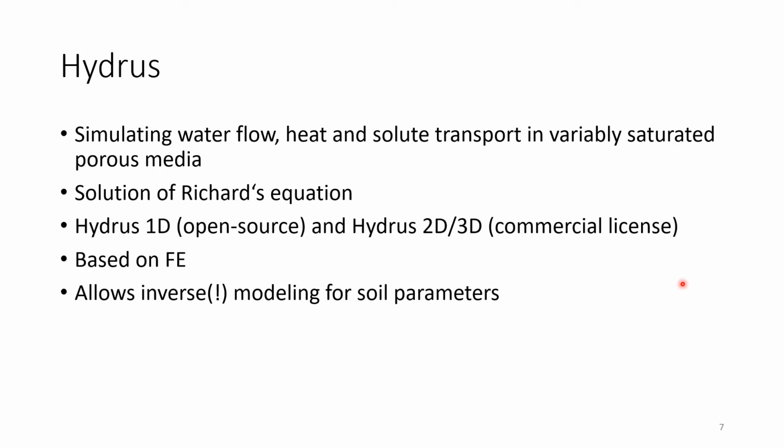A slightly different approach or slightly different focus is Hydrus. I was struggling with including it in this list because it's not strictly speaking a groundwater modeling tool, because Hydrus is very specialized on infiltration models. So it's not solving the horizontal groundwater equation, but it's solving the Richards equation, which is the mathematical equation for infiltration problems, and it allows you to couple that with heat and solute transport.